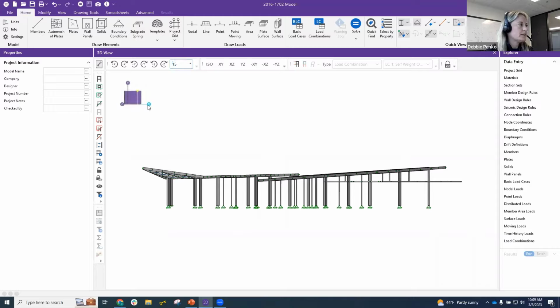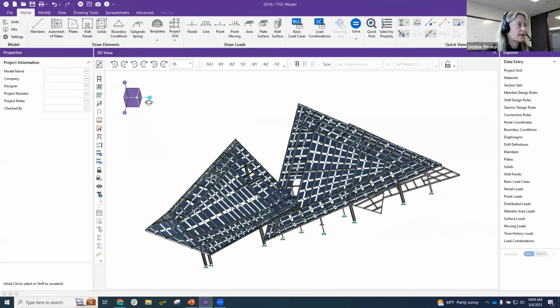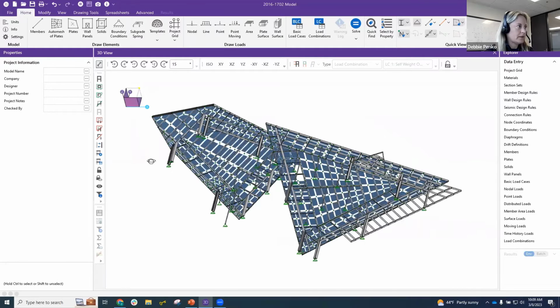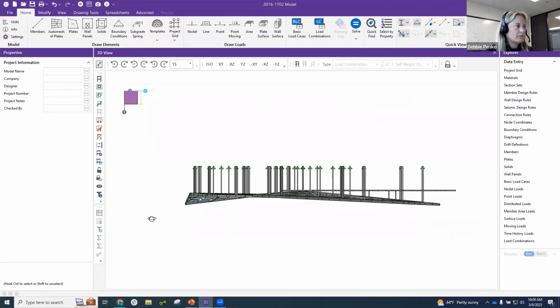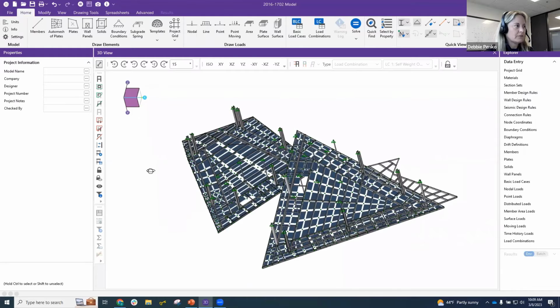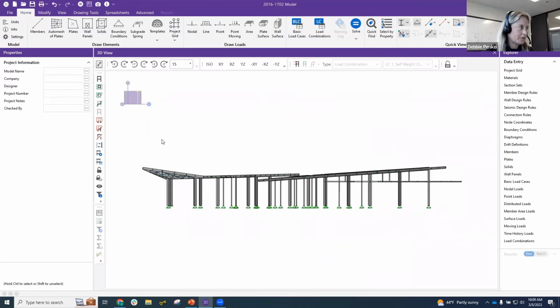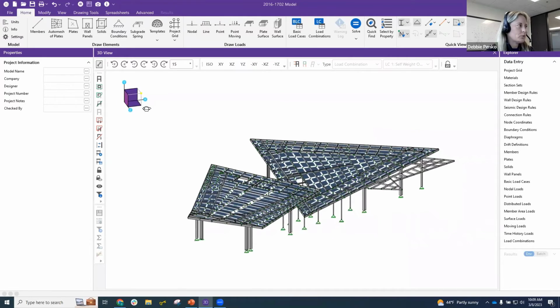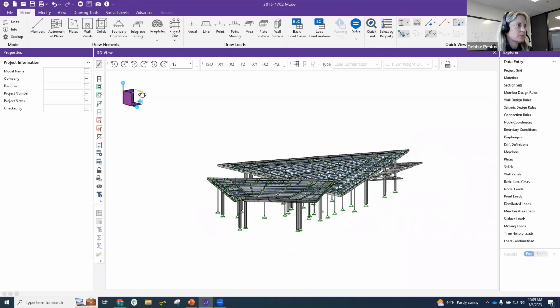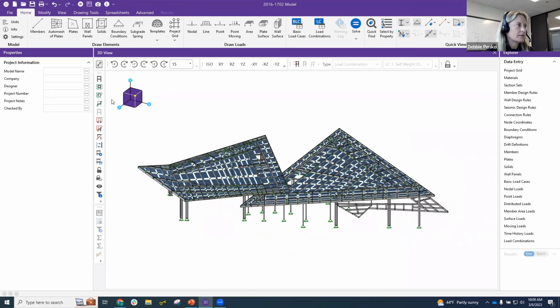The other thing we did is that if you hold your shift key and you hold on to that axis, you are rotating it. I think we got 45 degree turns on that. So I'm actually moving it in 45-degree increments. This, again, for a very complicated model might help you really orient yourself in the model. But you can always grab this and rotate it like this as well. I'm a big fan of this axis.